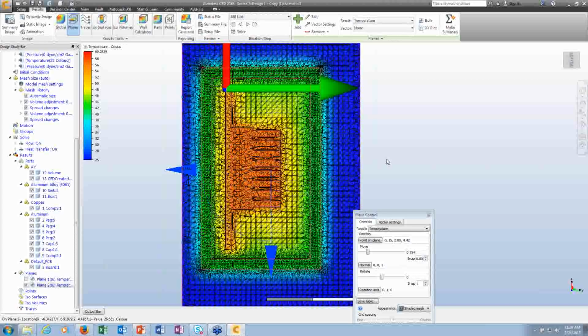So the question is, is it more work? Yes, it is more work. Is it worth it? Well, that's for you to answer. If it's easier or faster just to throw a fine mesh everywhere that's going to give you that definition between the fins and you don't care, then definitely that's the right answer. Don't worry about it and throw a fine mesh. If throwing a very fine mesh is going to really make the analysis go slow, then yes, it's worth it to spend some time creating those volumes and then have a model that you can run over and over again without having to wait a very long time to get results. So it's good to know that it's something that is available to you should you choose to go that way.